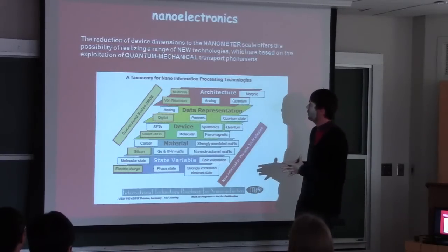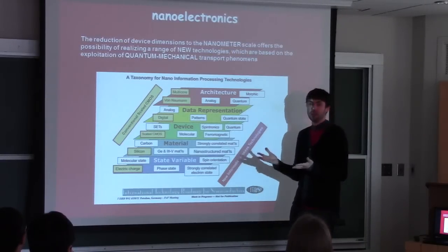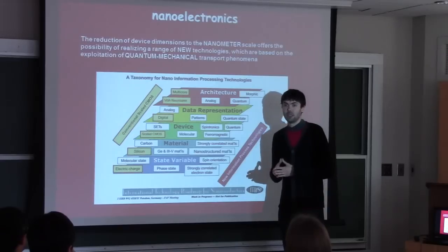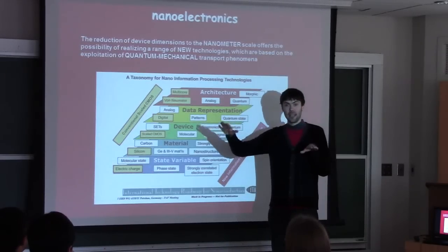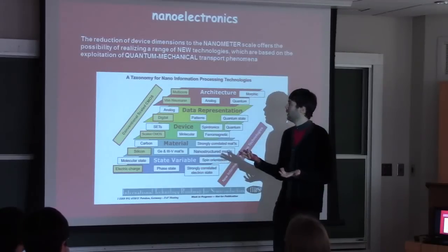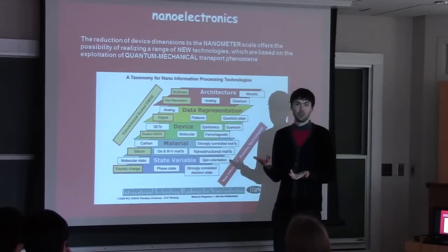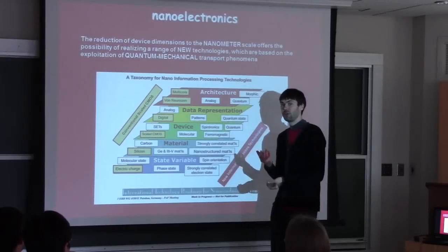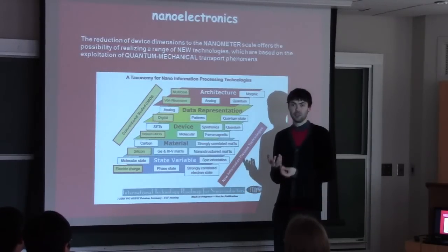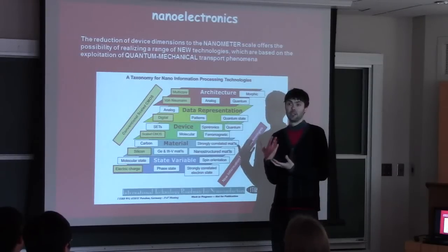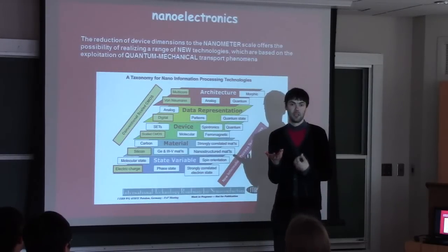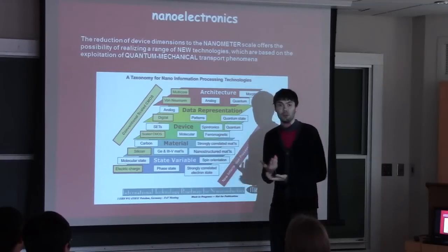So for example, currently the backbone of all this technology is a transistor. Like I explained, it is a gate, source, and a drain. But what if a gate is also spin dependent? So you're adding another degree of freedom into the functionality of this transistor, which can allow you to maybe implement a certain logic gate with these transistors with fewer operations.